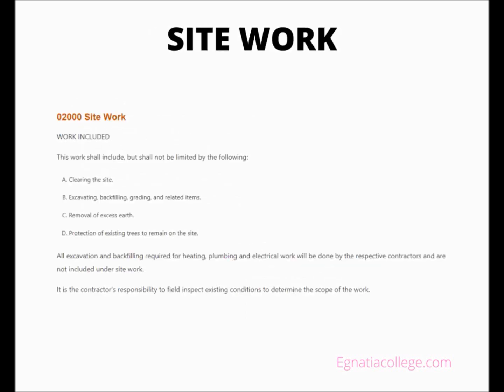Site work. Work included. This work shall include, but shall not be limited by the following: clearing the site, excavating, backfilling, grading, and related items, removal of excess earth, protection of existing trees to remain on the site. All excavation and backfilling required for heating, plumbing, and electrical work will be done by the respective contractors and are not included under site work. It is the contractor's responsibility to field inspect existing conditions to determine the scope of the work.